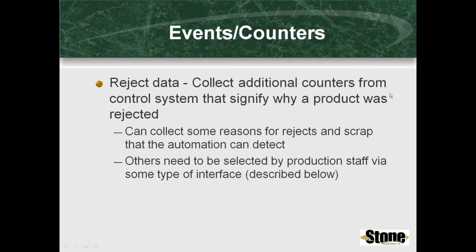What I mean by that is we're going to be taking a look here at a filling line. For example, if you had a filler and you had 500 pieces that came into the system and only 400 came out, meaning you had 100 scrap units inside that filler, you could, in theory, have 5 different reject counters that tell you how many of each of those different types of rejects happened inside that filler. So automated data collection systems can provide a lot more detail that will help you understand when these different calculations are outside their range or breaking the lower or upper control limits.